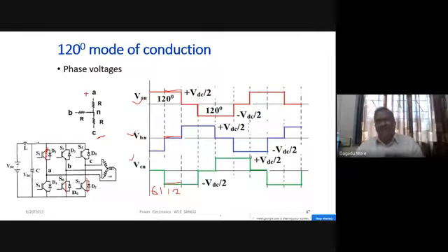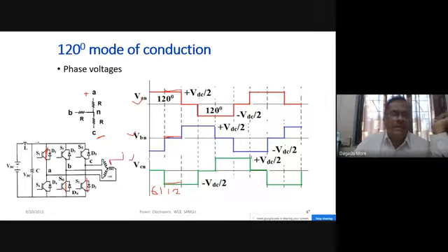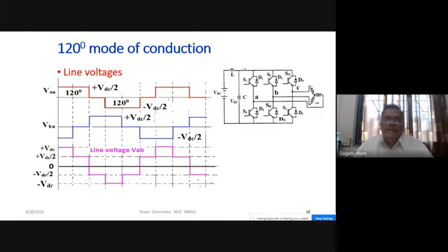We get 3 phase voltages where we created a star connected load, and the neutral point here will be N of this particular star point. And then we get these phase voltages. The phase voltage is a quasi square wave, whereas the line voltage is a quasi square wave too, that is the difference. And now once we know VAN and VBN, we just copy them here.